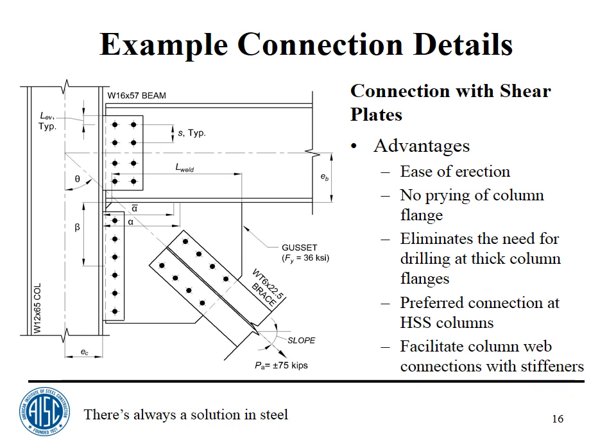Okay. Next question. If you had multiple columns of bolts on an end plate connection, for example, how would this affect the behavior of the connection? How would the outer column of bolts affect the prying action analysis?